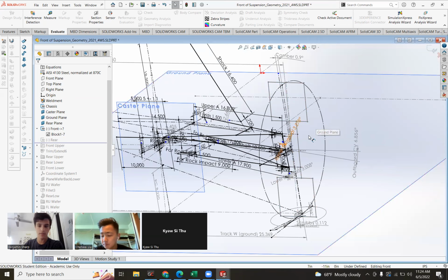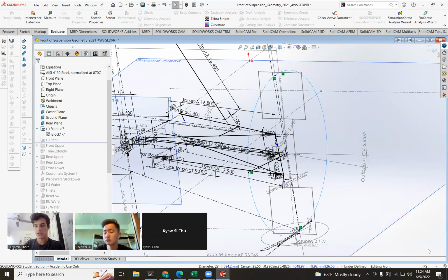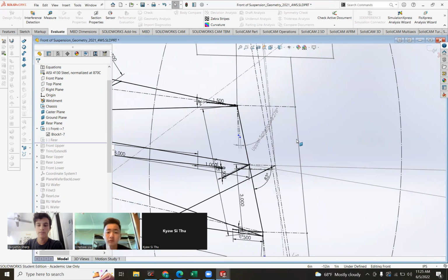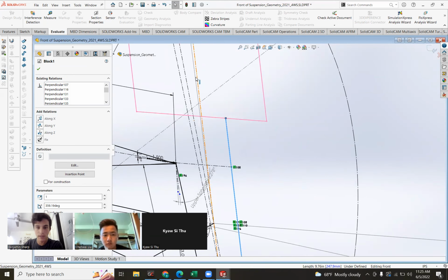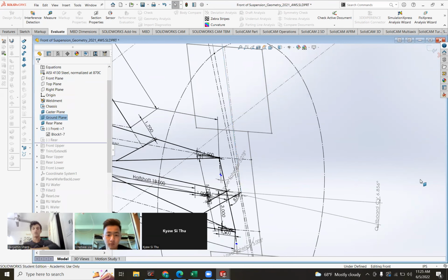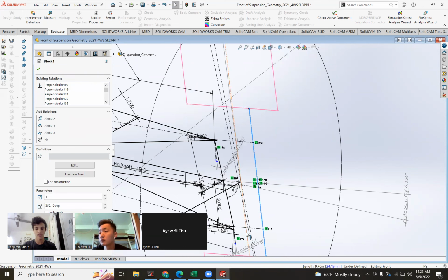The important thing to take from them is the diameter of the tire. We have to make sure that's right, and you can edit that if you need. And then these two lines, there's one right here and one right here. Those two lines allow the wheel to have its axis set and then to pivot. And this is the line you use to enforce that pivot.